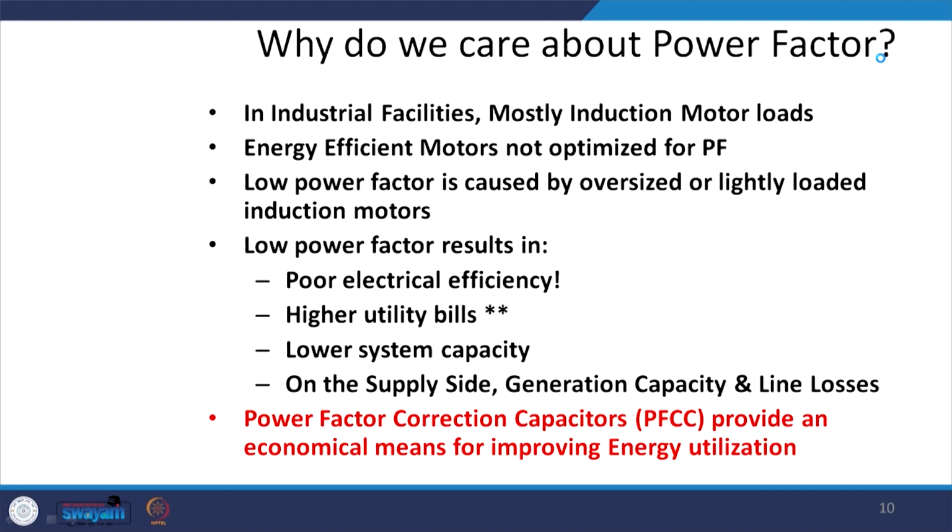So, in industrial facilities, mostly we have induction motor loads, energy efficient motors not optimized for the PF. So, we can generate low power factor. Low power factor is caused by oversized or lightly loaded induction motors. When you load that machine properly, it will take a good power factor, but if you are not loading it, predominantly it will have a magnetizing component, and thus it will degrade the power factor.